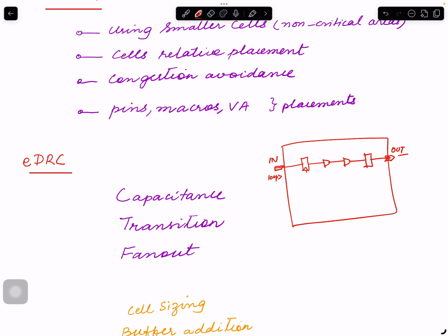Let's say you know the output side connection, so you think that it will have 10 femtofarad capacitance. You apply those, and what the tool does is propagate those. This is the wire. It knows how much R and C it has, so it moves that and determines how much transition time here. Then it also determines the capacitance of this one. I already talked about this during timing, but it determines capacitance and transition in each node.